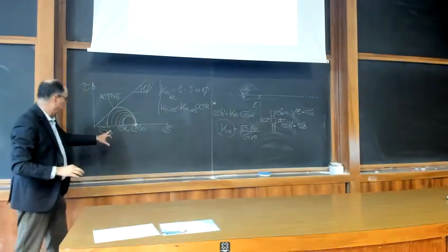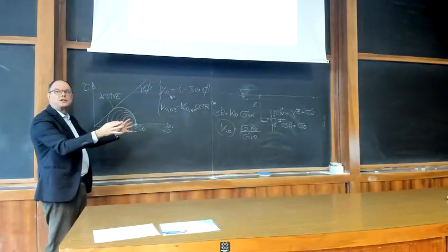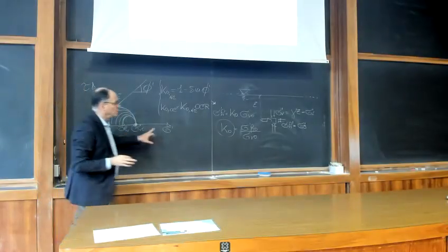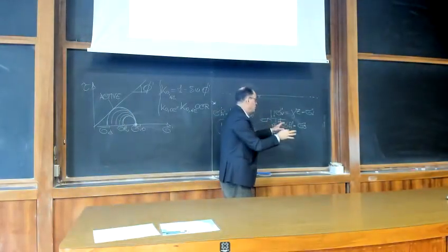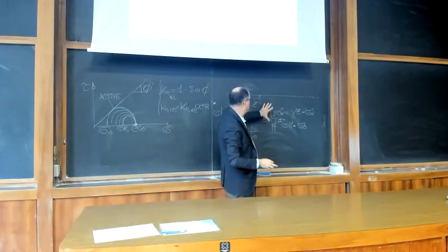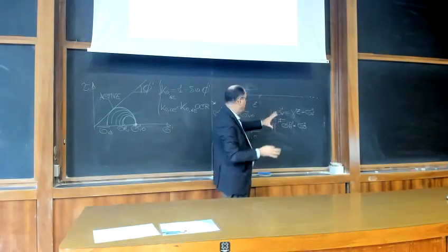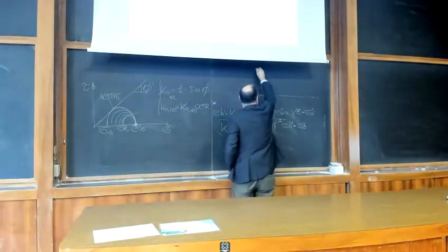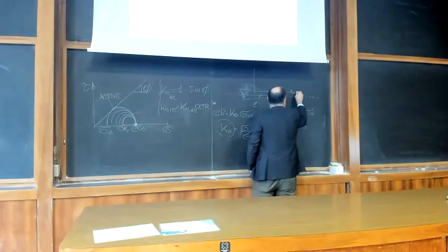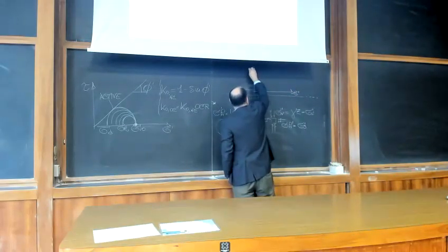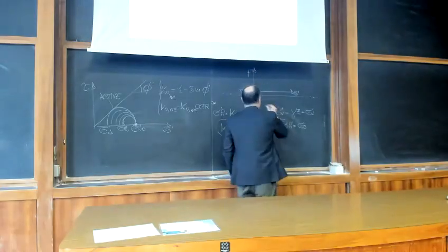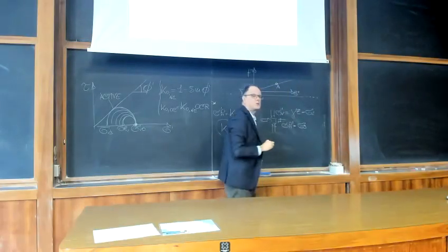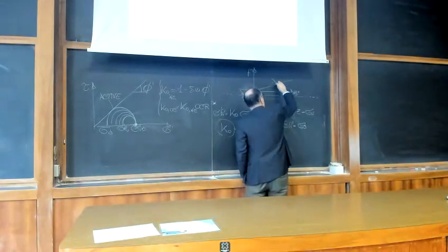Okay, so in order to get to this, you have to reduce the horizontal stress, keeping constant the vertical stress. You are in this condition, and you have to keep constant this. So let's assume that the depth is always z, and you reduce the horizontal stress. If you think of our S prime T prime plane of our load path that we discussed last week, we are going in that direction.